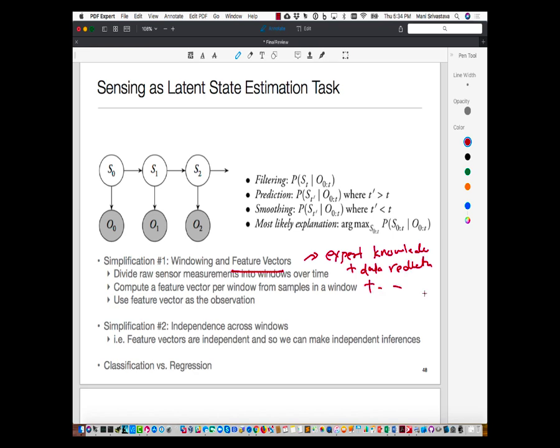Do you see any other advantages for features? You reduce the data that you're working with? I already know that, data reduction. Prevents overfitting? In what ways? I don't see that. Yeah, it's kind of like expert knowledge. Well, the third very important one was, what if my underlying sensors were diverse or were sampling at different rates? By going to features, I bring heterogeneous sensors into a common framework. So features cope with heterogeneity.